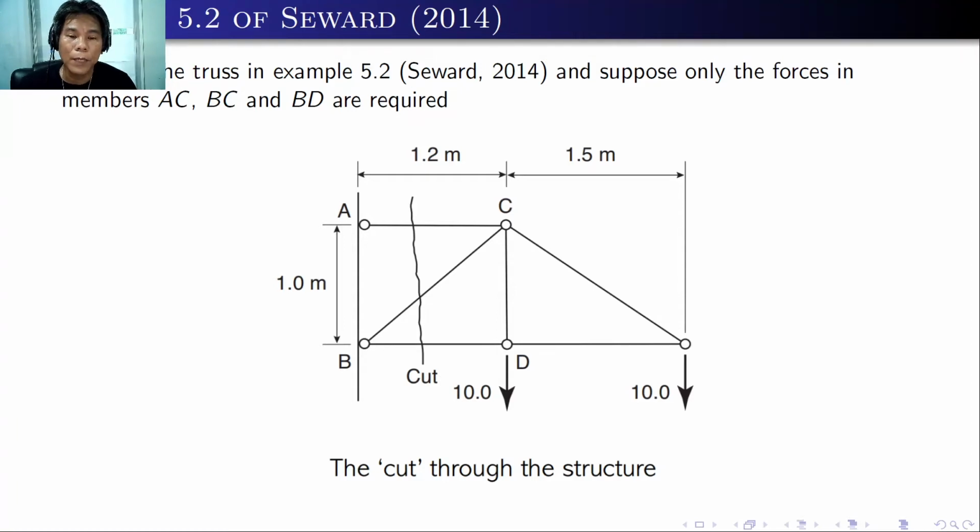If you cut BC, then the shape ECDB will try to have a parallelogram shape, meaning point C is moving towards point B. So this is in compression.